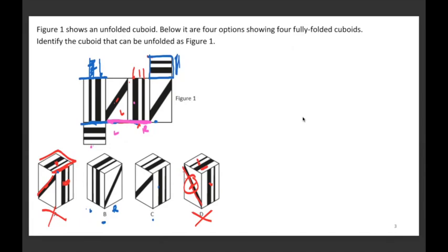There is also one more way of looking at it, and I tell you the option C, and you may be confused, but option C can be worked out here this way also, where the slant height, the thick line and the thin line come here, thick line corresponding to the slant height and thin line corresponding to the other edge. So that works out here. And then if this is supposed to be the left and this is supposed to be the right, in that case, this part has to be the top view that we see in C. The orientation of that is working, not a problem. These two are working out perpendicularly, which is not any issue. So C is also fine.